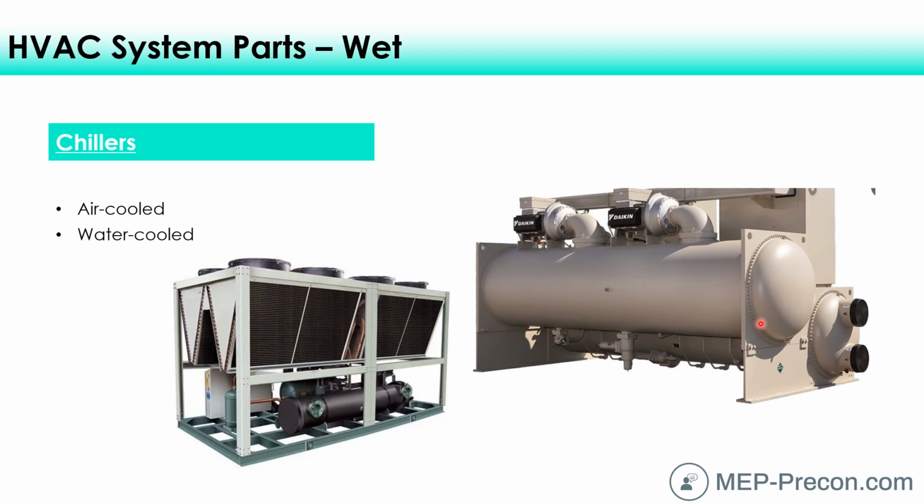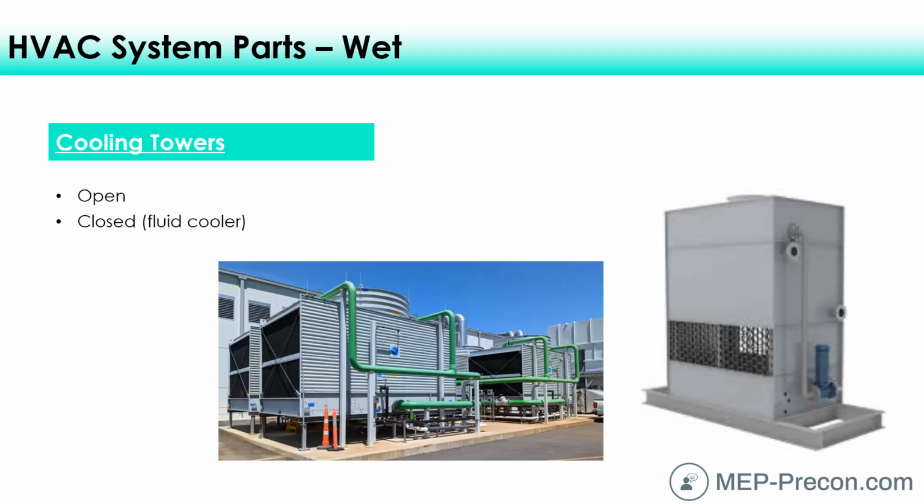Once we go through the refrigeration cycle, we've moved the heat of the building from the fan coils through our hydronic water system, and we have exchanged that heat. The heat's finally in this water. Where does that go? Well, that water is going to go to a cooling tower, that you may have heard of. And so we're going to pump that water from the condenser barrel. Again, if that's unfamiliar, make sure that you watch the video on air conditioning.